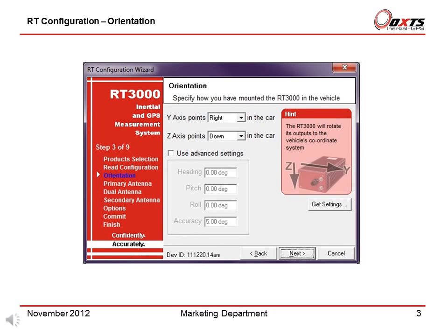The RT gets its initial heading by assuming that the RT velocity or slip angle is small. If the definition of the vehicle x-axis is incorrect in the RT, then it will not initialize correctly when the vehicle drives forward. The orientation of the RT in the vehicle is normally specified using 3 consecutive rotations that rotate the RT to the vehicle's coordinate frame.